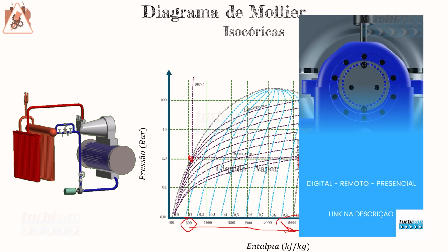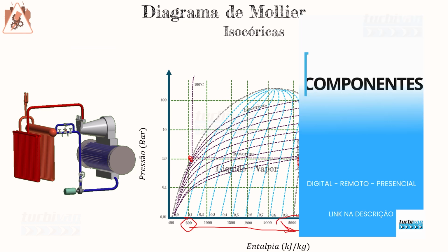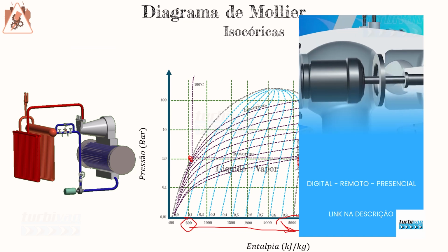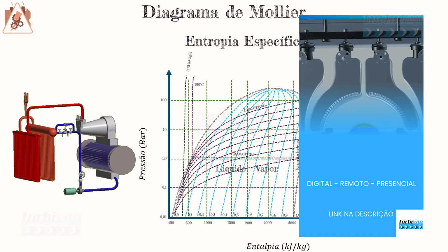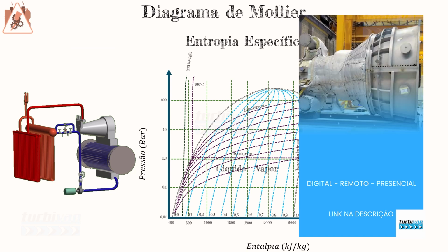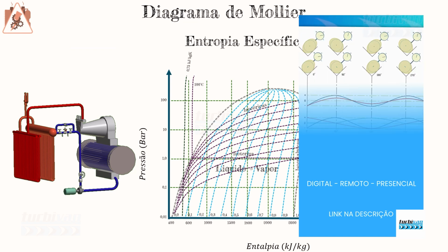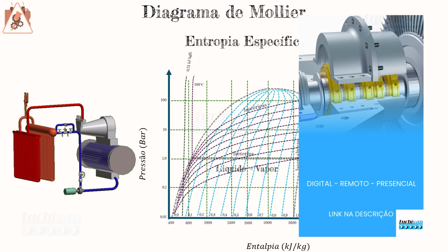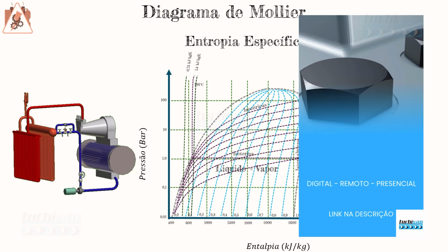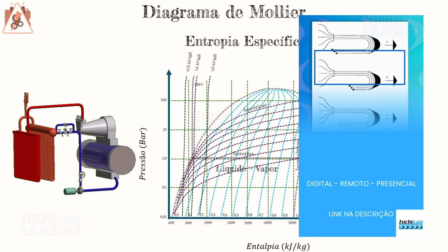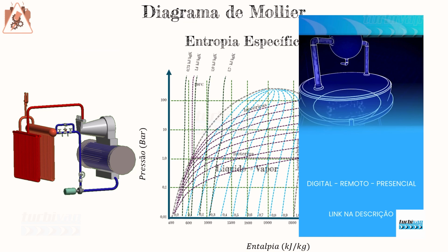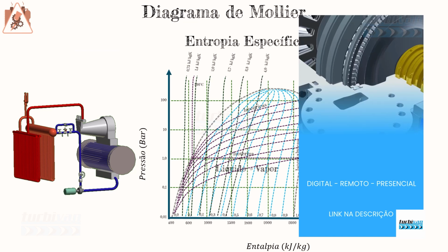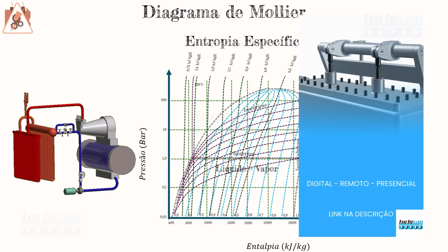In this case, we are studying, finally, another extremely important variable that the diagram specifies, and that's right here, our isentropic lines. We notice the value of the isentropic lines, and we go building them on top of the chart. So, if we think about Carnot's machine, or even one ideal turbine, we have to work along an isentropic line, so these are the entropy values that cut the Mollier diagram. Here is just an example. It's very easy for us to start understanding.